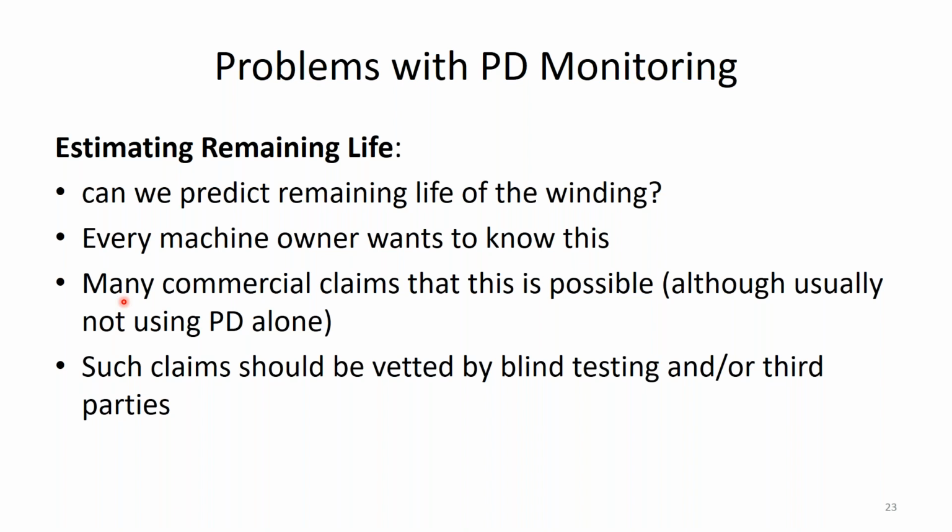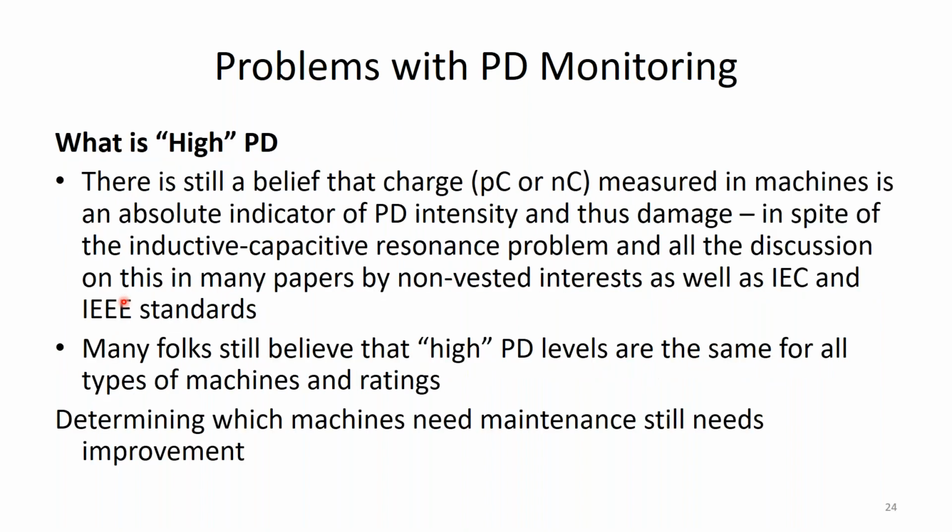Certainly not using PD alone, and not even using any of the other diagnostic tests. EPRI has spent a lot of money trying to validate those things in the past, and under third-party validation, it just hasn't stood up. Okay, so if people are claiming remaining life and all that kind of stuff, make sure that has been independently validated in blind testing, where the vendor was not involved. To my knowledge, I know of nothing that allows us to predict remaining life, and I want to, but I don't think it's possible yet. Maybe not ever, at least not with electrical measurements on stator windings.